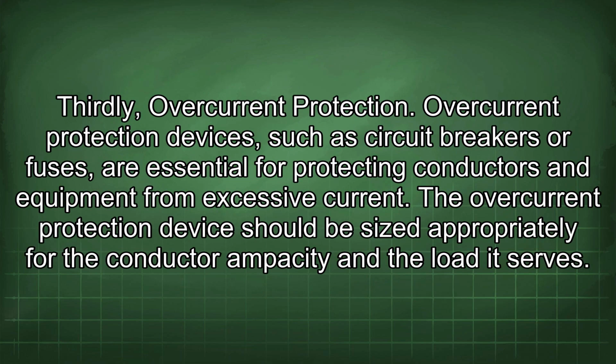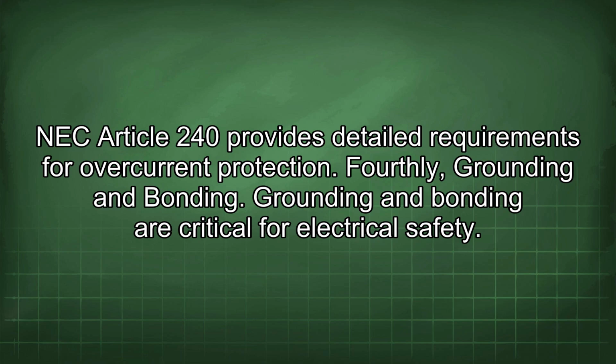Thirdly, overcurrent protection. Overcurrent protection devices, such as circuit breakers or fuses, are essential for protecting conductors and equipment from excessive current. The overcurrent protection device should be sized appropriately for the conductor ampacity and the load it serves. NEC Article 240 provides detailed requirements for overcurrent protection.